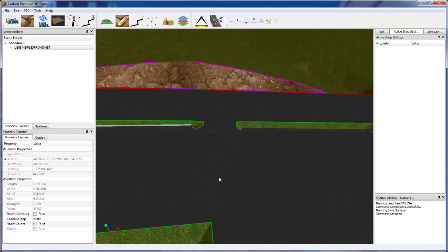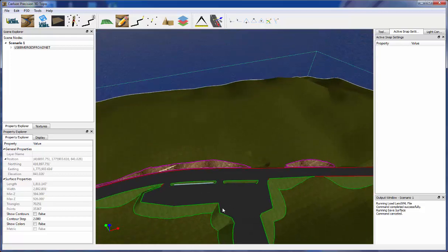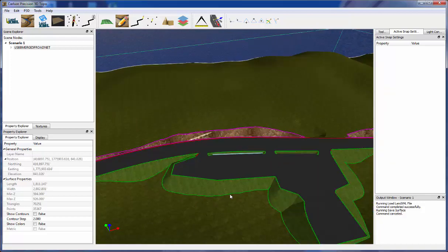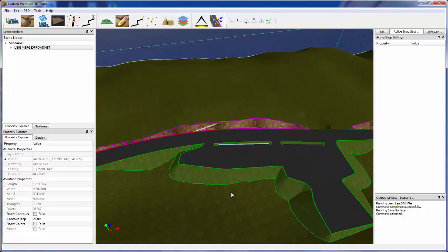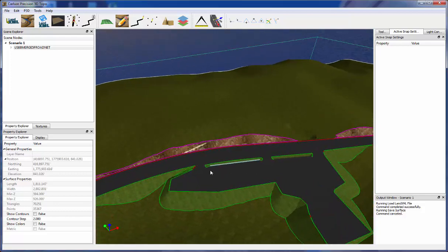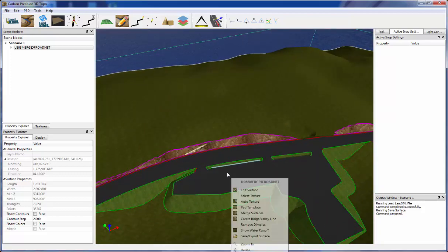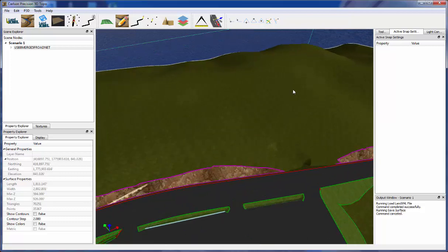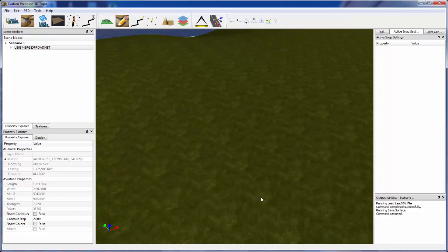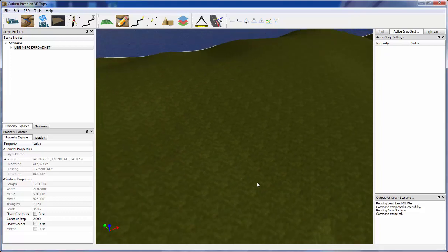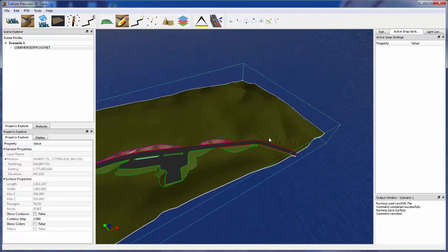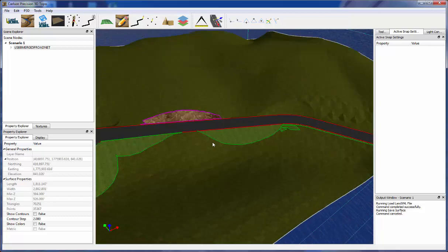It's the basics of navigation. So we have the middle mouse scroll wheel scrolls in and out for zoom. If you hold that mouse wheel down and move the mouse, that's our pan command. If you hold the left mouse down, that's going to give you your rotate. If you double click anywhere on the surface, it's going to zoom to that point, and basically it's a 50% zoom. If you control double click, that's a zoom out, basically by the same amount. So it makes getting around surfaces pretty quick and easy.